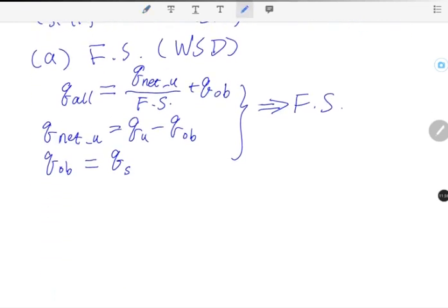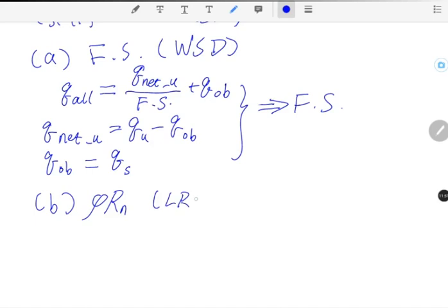And part B, for the factored geotechnical resistance, phi Rn using LRFD, we need to know phi factor for shallow foundations is usually selected to be 0.5, and Rn, geotechnical resistance, is equal to the QU you calculated previously.